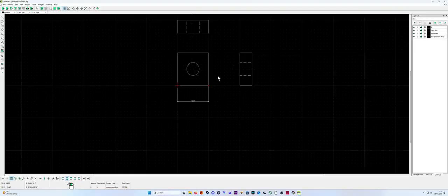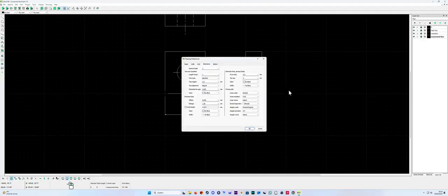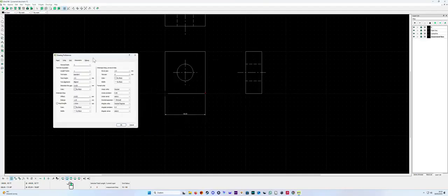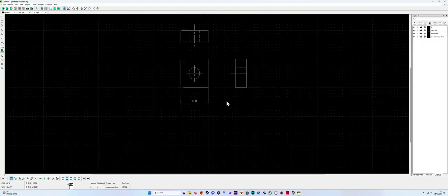But you see, when you look at it like this, it is small. You say, well, damn it, why is that so small? But you can change it quite easily. You're going to options, my mistake. You say current drawing, and then you get what you did in the beginning. Now you can change it also. So let's put a general scale of 2. Leave the rest, and then look at it. That's a lot better. This looks good.